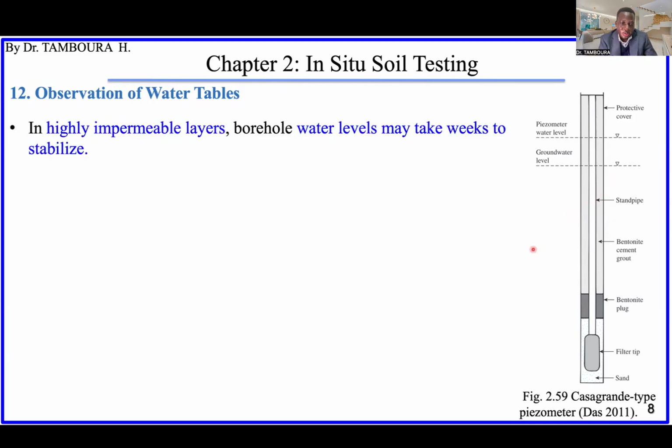If we are dealing with soils that are highly impermeable, the borehole water level may take weeks to stabilize. So you cannot dig and immediately take the water level to say, this is the water level. Sometimes it takes weeks before you know the stable water level.